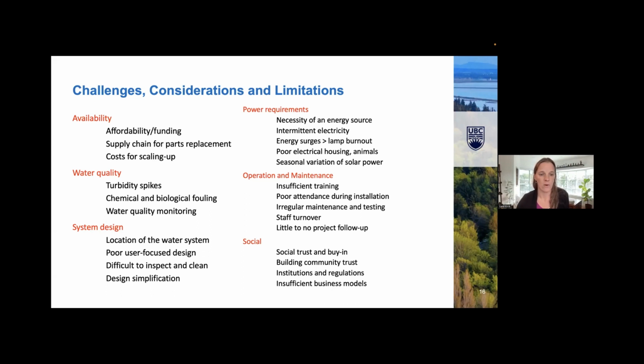And then also water quality monitoring, and when does it make sense to install monitoring sensors, and then what parameters would you want to monitor for? But basically, whatever you're feeding into the UV lamp, you need to keep it within certain parameters for the UV to be effective.